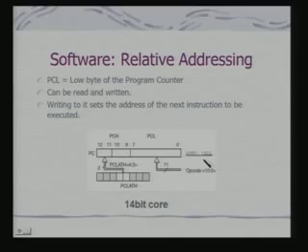Now, you have got relative addressing and software relative addressing as well, because when you are doing any of these goto and call, what is the significance of the fact that the most significant bits here are coming from the PC latch high register? It means all your goto and call are in a sense PC relative, relative to the current PC value, because of the current PC value, the most significant bits are loaded onto PC latch high.